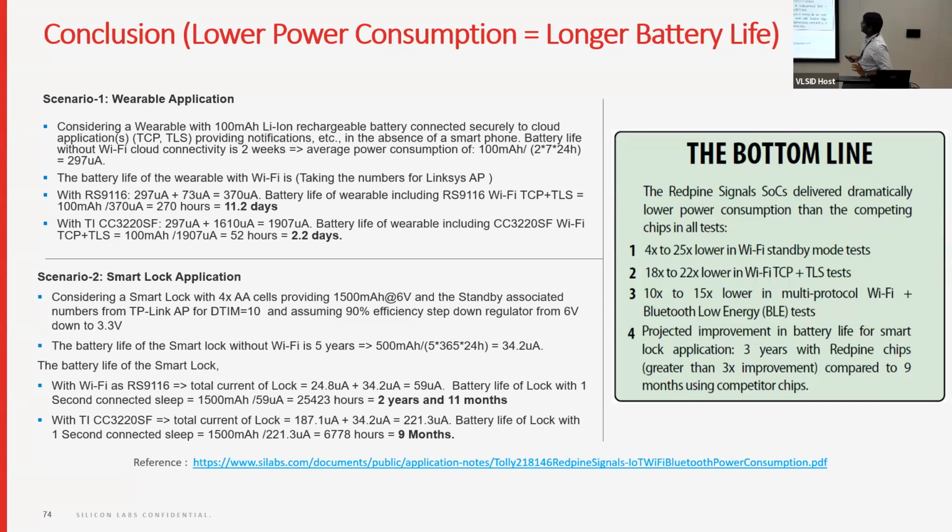The battery life of that particular wearable is 100 milliamp-hours divided by the total current, and we get around 270 hours, which is 11.2 days. The same calculated with the third-party vendor gives around 2.2 days. So that's the difference in the power consumption.